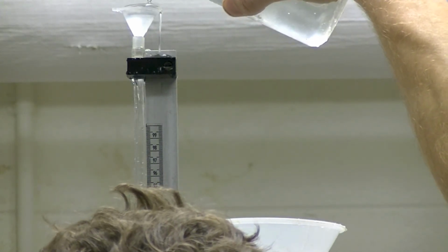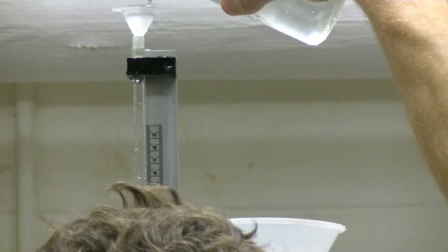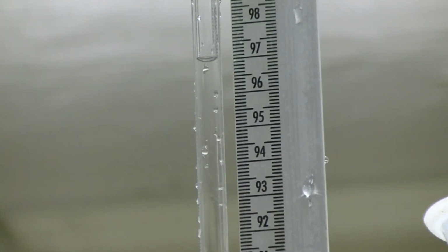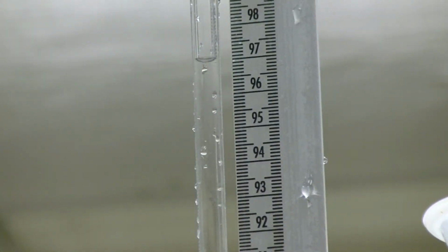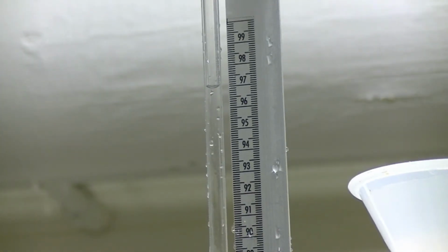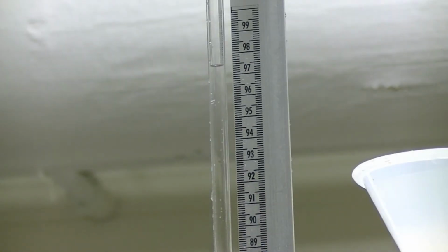Once flow has stabilized and no air pockets exist in the manometer tube, close the valve at the base of the manometer. Adjust the water level so that a starting head value can be read off. Record the starting head value. While starting a timer at the same time, release the base valve below the manometer and introduce flow into the sample. Notice the meniscus in the small manometer drops.